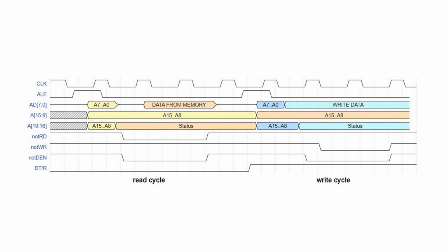So if we start to think about CPU timings, because understanding of CPU timings is important if you're designing a CPU system, we see from the databook that a memory read or a memory write take 4 CPU clock cycles if there are no wait states. And in this diagram here we can see AD7 down to 0, and we can see at the start they carry address data, later they carry data from the memory, then they move back to address data.